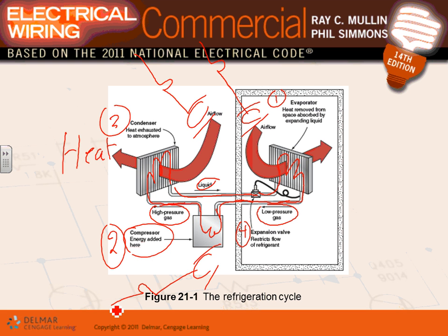Right here, can you guys see that one right here outside, the condenser? You can condense by throwing air, or you can condense by removing the heat through water. You can remove the heat here by circulating this through water, and the water will pick up the heat and throw it outside. So this one is air. They're removing it right here through the air. The coil is very hot, throw the air right through it, pick that heat and throw it outside.